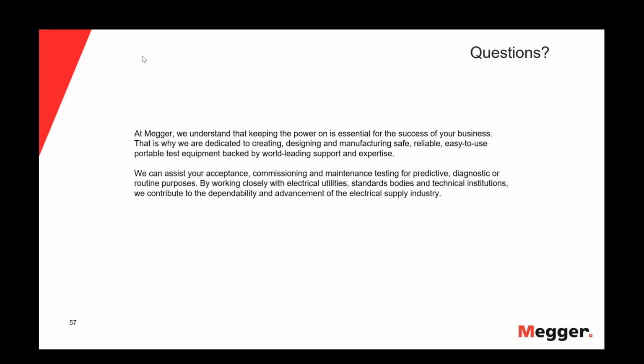All right, thank you, Robert. I want to squeeze in one last question today, and while I have you, I'm going to send it over to you. For tan delta testing, based upon the difference between 1.5 U-naught and 0.5 U-naught, what can it tell us about the condition of the cable based upon the IEEE and IEC standards? Is that for me or for Henning? Sorry, that'll be for you, Robert.